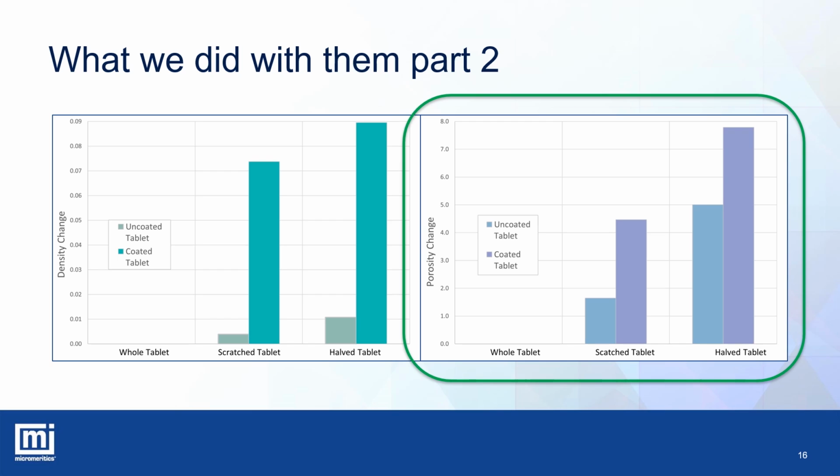This is interesting, and is almost certainly telling us something about how these tablets were formed. These are commercial tablets, and I have no prior knowledge of how they were actually made, but this data pattern strongly suggests the tablets were both made with a very similar process. Most likely a powdered or granulated mixture was loaded into a die press and then compressed into the tablet to give this distinctive pattern of a harder, well-compressed outer that is less porous than an inner portion of the tablet that is less well compressed and more porous. The aspirin will then have gone on to a second coating step.